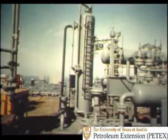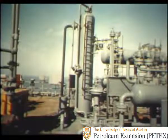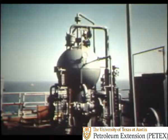Vertical separators, such as this one, are generally used for low pressure service, but on some platforms are used for high and medium pressures also. The spherical separator is more compact and cheaper, but it has limited separation space and liquid surge capacity. It is therefore used mostly on low-volume remote platforms.